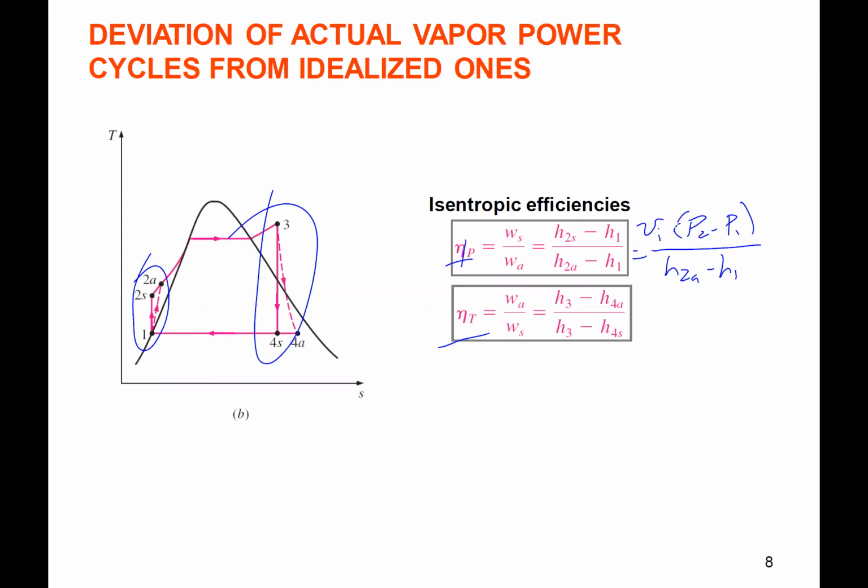The difference is we have, say, water in this case, so we've got to use our states and our property tables to get enthalpy at 1. We know h2s is isentropic from 1, so we could utilize that information, and if we were given isentropic efficiencies, then we could utilize the equation to solve for 2 actual. Same with the turbine: given isentropic efficiencies, utilize state 3 information. Knowing it's isentropic, we can get 4s, and then utilizing this equation, we can get our 4 actual.